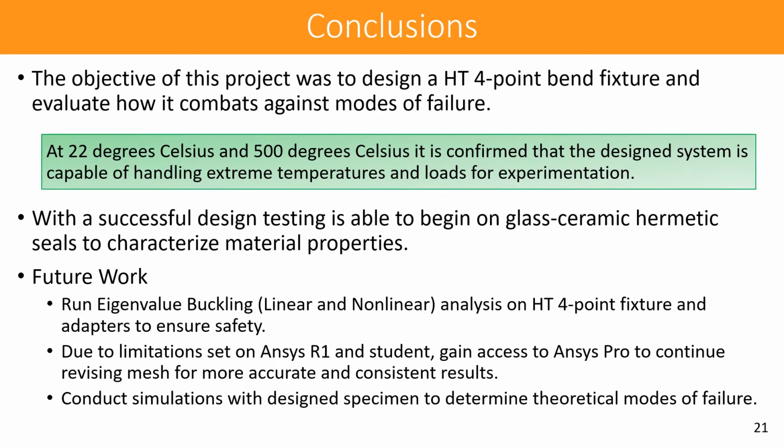The future work for this research is to continue to run eigenvalue buckling, linear and nonlinear analysis on high temperature 4-point fixtures and adapters to ensure their safety. Due to the limitations set on ANSYS research and student, I would like to continue to revise the mesh for more accurate and consistent results, as many times when optimizing the mesh, I would get many errors with the software that I currently have. Lastly, is just to continue to conduct simulations with the design specimen to determine the theoretical modes of failure for these types of tests.